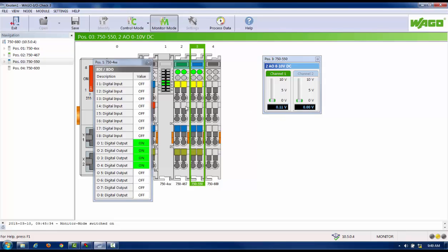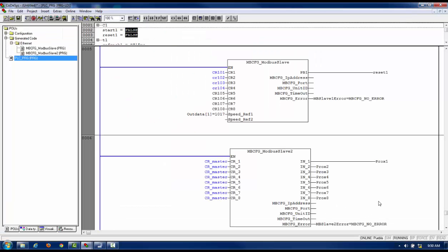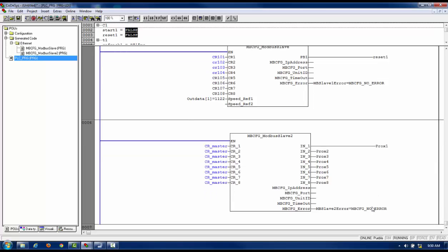So again, just showing you, setting this up with an 880 as the master device, an 880 as a coupler, and then a Speedway node as well as a drop on the network. And just showing it's working here. And just to show you some other things too, if for example I lose communications, then I have this information here as far as the data, what type of error condition I might be having with the device based on my communication. So again, that could be useful from a troubleshooting diagnostic standpoint as well.